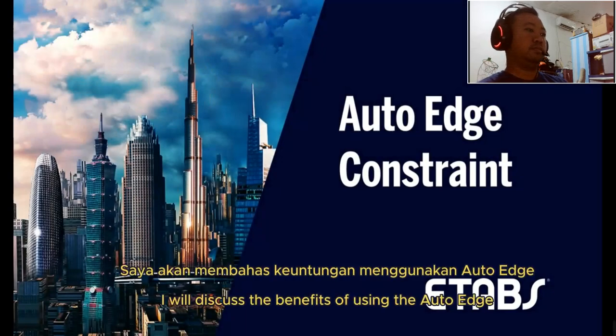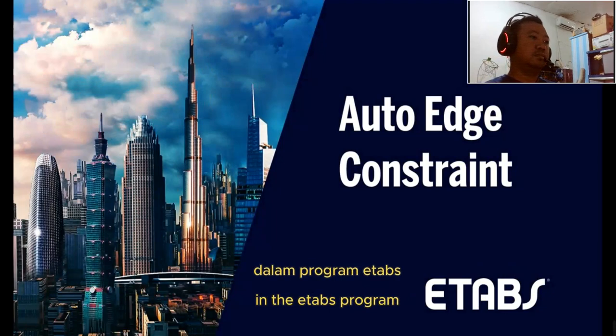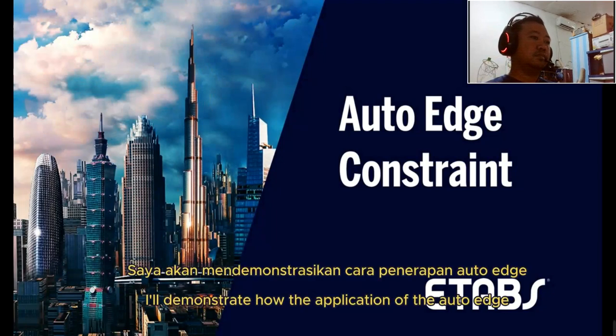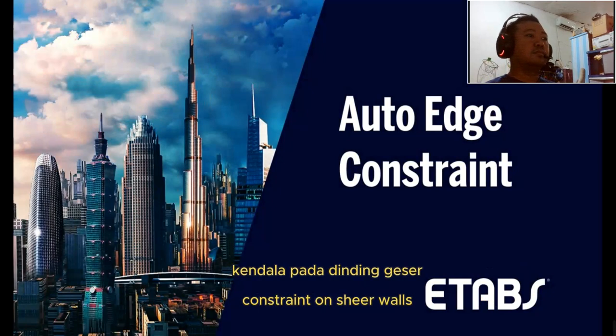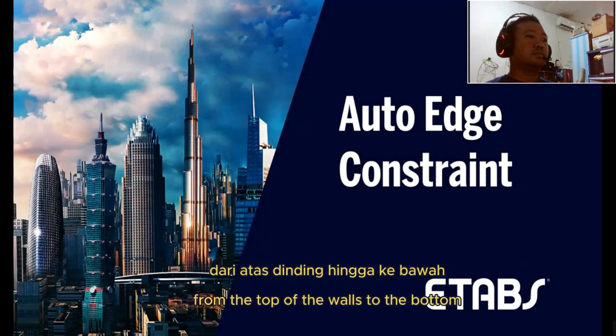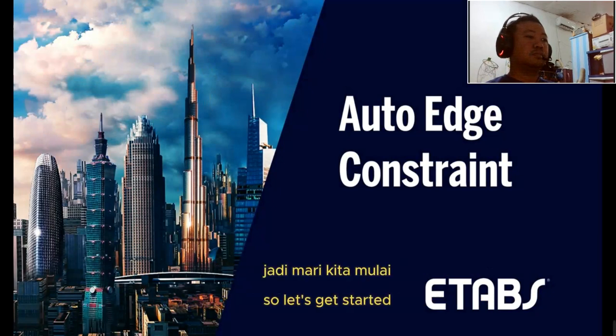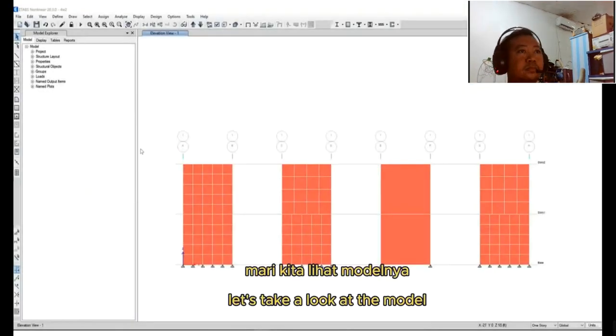In this video, I will discuss the benefits of using the auto edge constraint assignment in the Etabs program. I'll demonstrate how the application of the auto edge constraint on shear walls will affect load distribution from the top of the walls to the bottom. So let's get started. Let's take a look at the model.